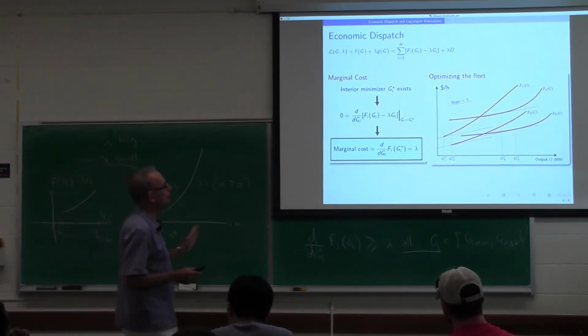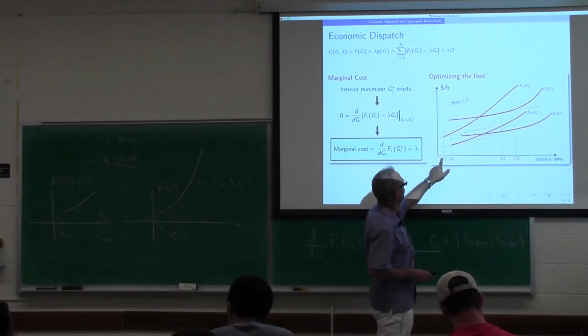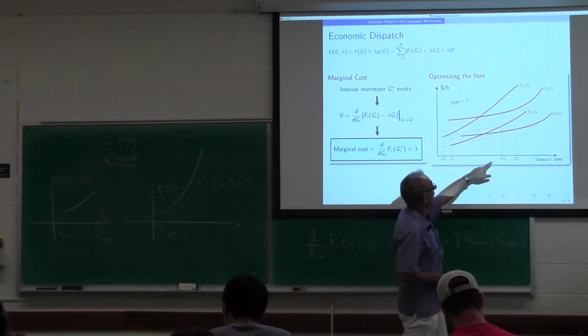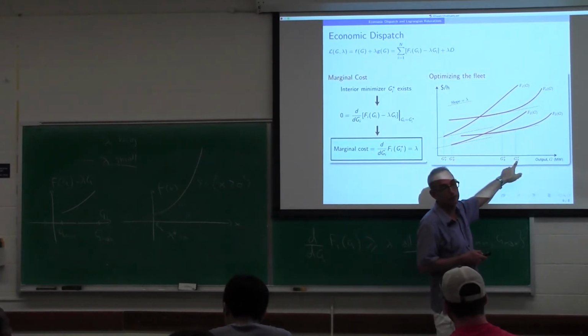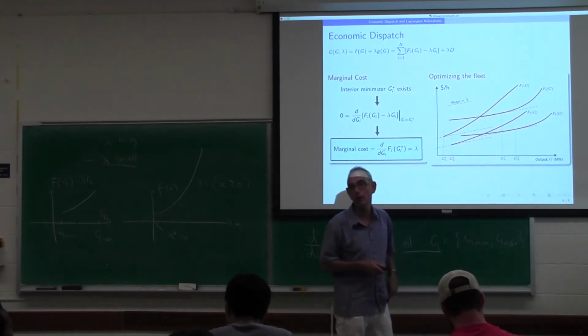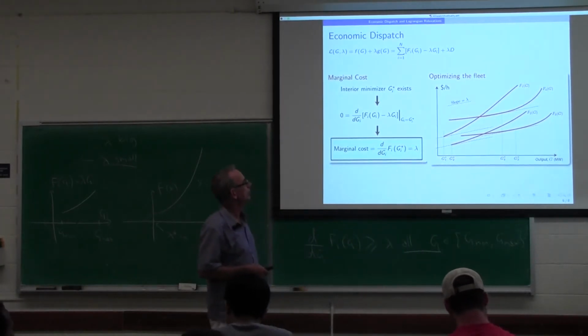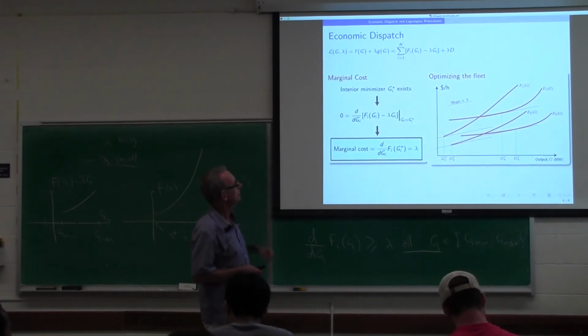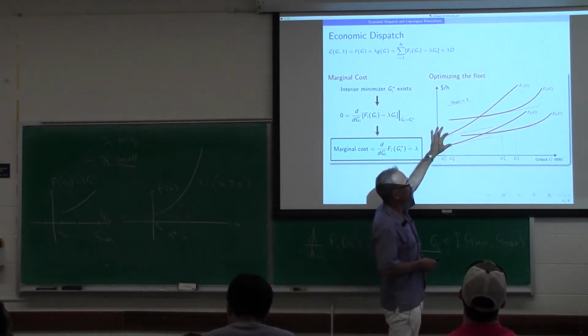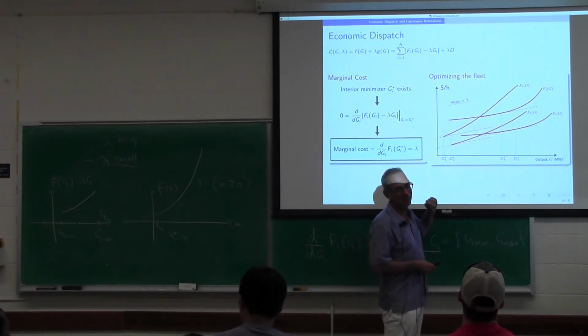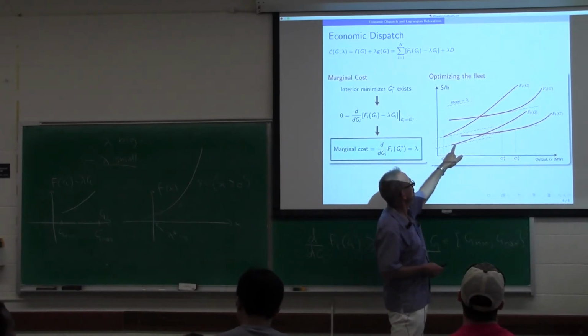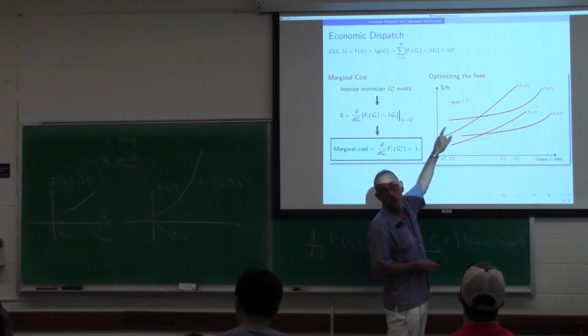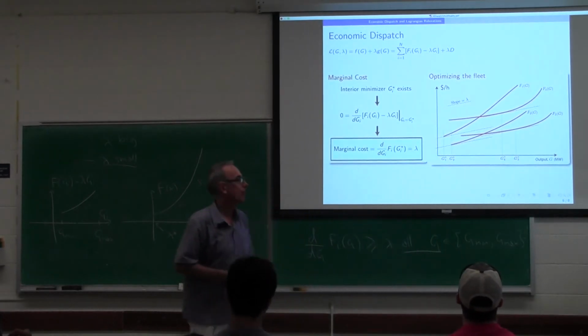All right, so here we go. We've got our allocation. With this lambda, we have G1 at its min, G2 at its min, and G4 and G5 require calculus. So these guys are easy because they go to their lowest value. And take a look, it's not what you might have guessed. The actual costs are very low, and yet you're not using them. It's not obvious that you would want to shut down or put generators 2 and 1 at the lowest levels.